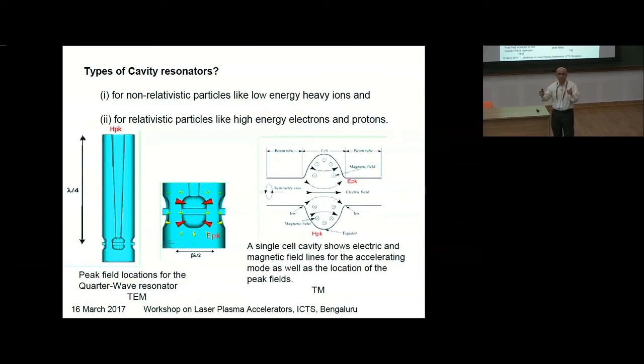You know about the sound wave resonators, where you have a lambda quarter wavelength, and you blow a particular frequency, it resonates. At one end, which is the node point for the voltage and the antinode for the current, and the other open end is the node point for the current and the antinode point for the voltage.